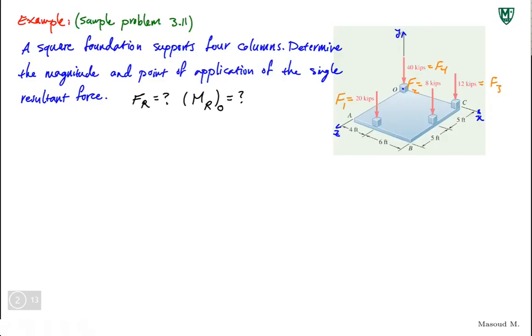All right. So for the first one, resultant force, it's pretty much a summation of all the forces I have. I have 4 forces, 1 to 4, so it would be F1 plus F2 plus F3 plus F4. And these are all vectors. Now, because all these forces are parallel, they are acting in the same direction. So it's pretty straightforward to find this resultant force or summation. If I take the upward as positive, always choose one direction as positive, take upward as positive here because y is upward, so it's positive.